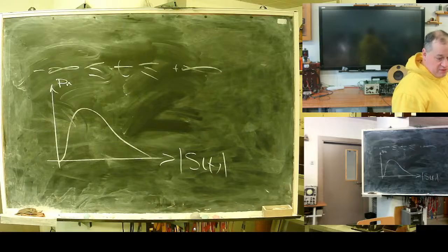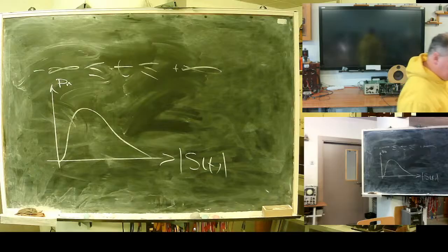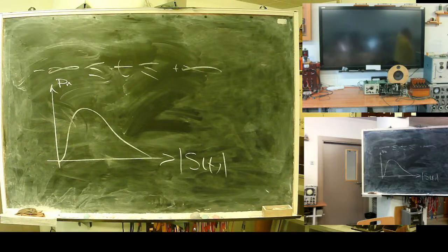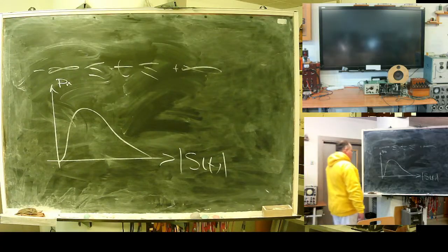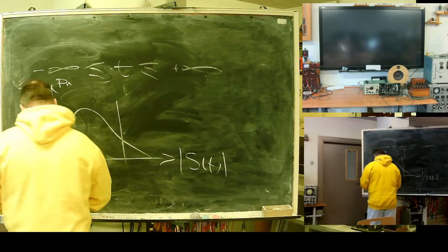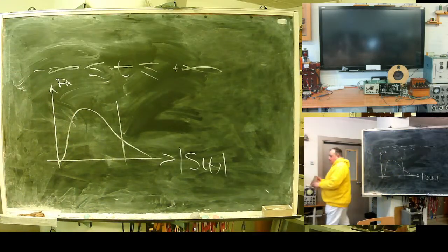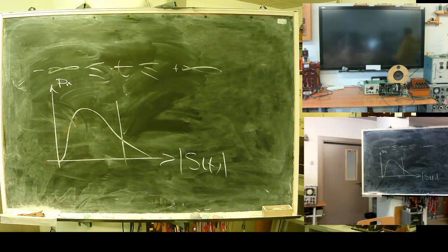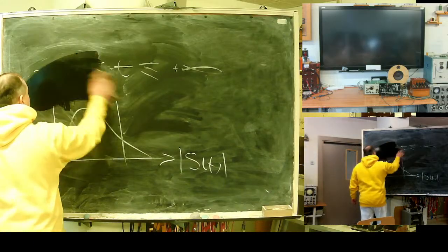After that it can burn. But I need to ensure operation at the maximum possible current, 200 amps within 5 seconds. Here is my test signal. If my device is operational at 200 amps, it will be operational in any case. So we select the maximum possible and substitute the probabilistic signal with a determined signal ensuring operation.